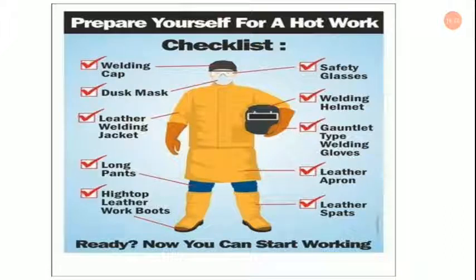Spaces that do not meet these requirements should be equipped with mechanical ventilating equipment that exhausts at least 2000 CFM of air for each welder, except where local exhaust hoods, booths, or airline respirators are used.